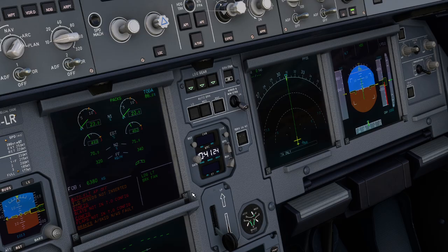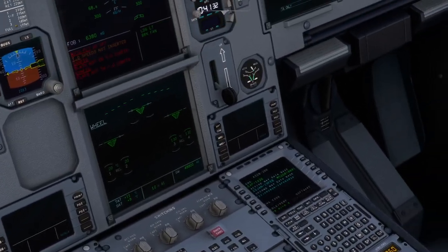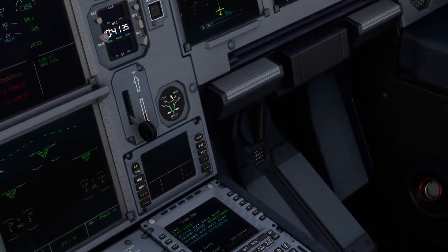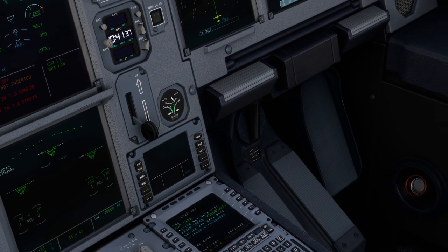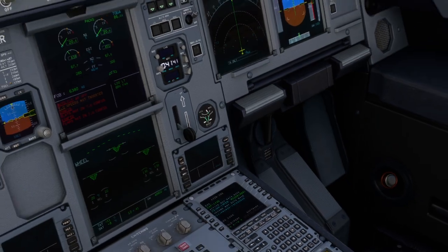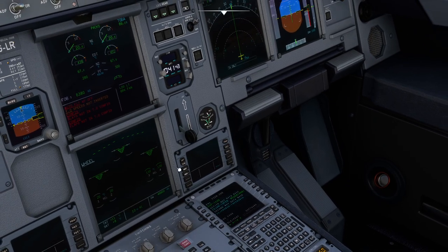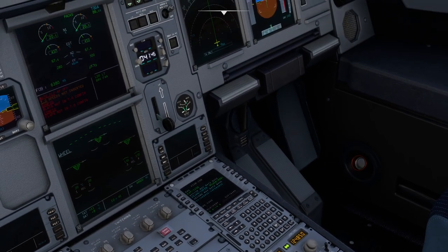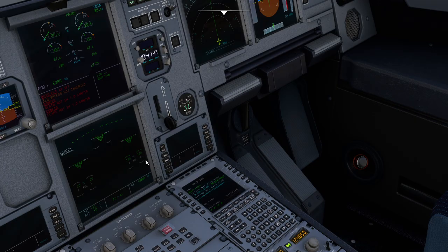And also we have turned up our fans, and let's see whether it will move forward. We are also looking for the pressure, whether there is a brake pressure issue or anything as such. But what we can commonly see is our right wheel is about 130 Celsius.